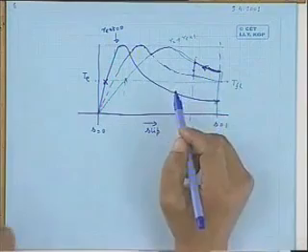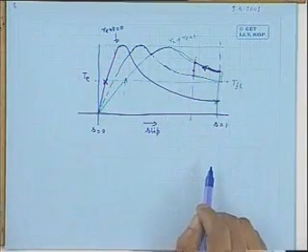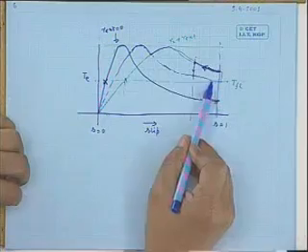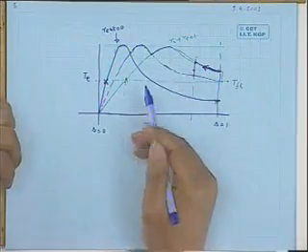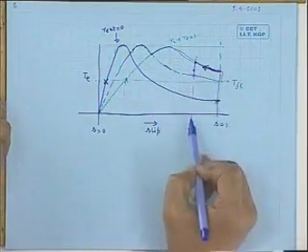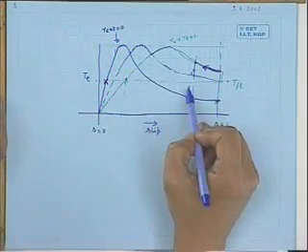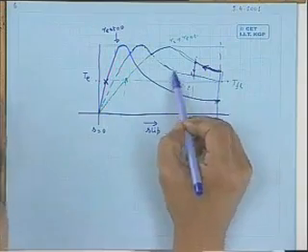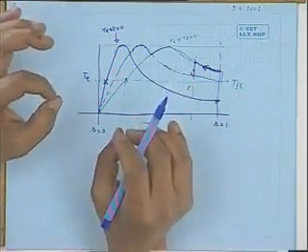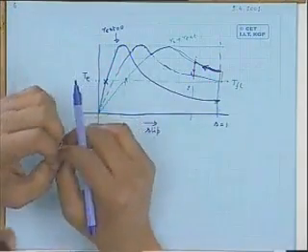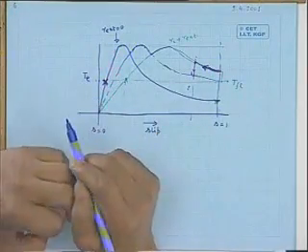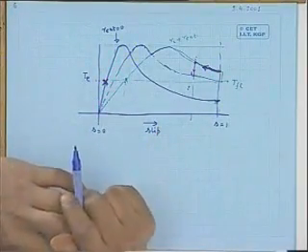So, of course, we are interested in the final operating point. It will come nicely here. Of course, we will be changing R external continuously. But to understand what is really happening, R external of 10 ohm was there. Now it is suddenly made 8 ohm. Then corresponding to 8 ohm, the characteristic itself is changed. And the slip cannot change instantaneously like that. The point of operation will jump from one characteristic to another and will move along that characteristic so long as you are not once again varying that resistance. Like that it will go and finally settle here.